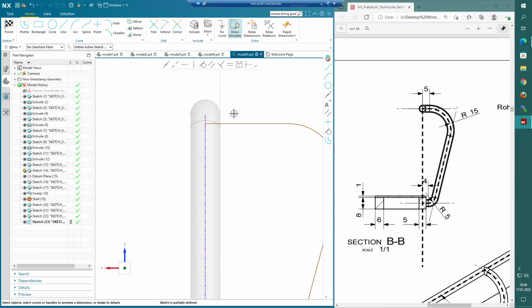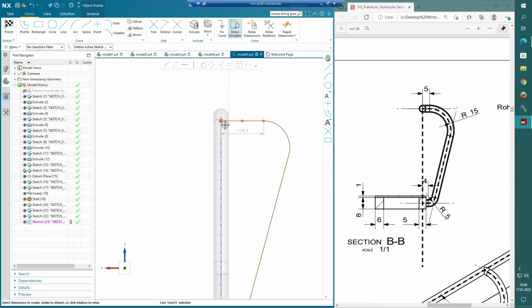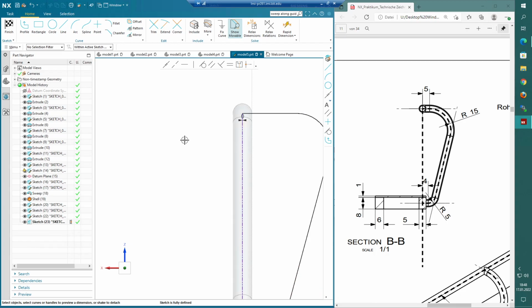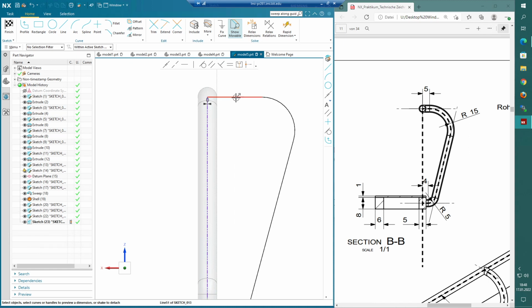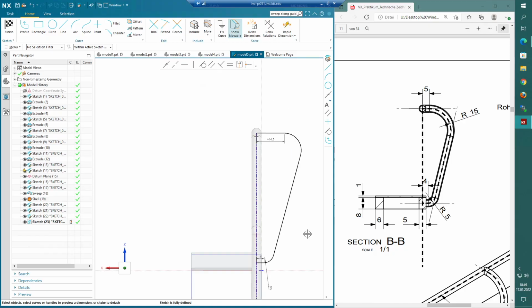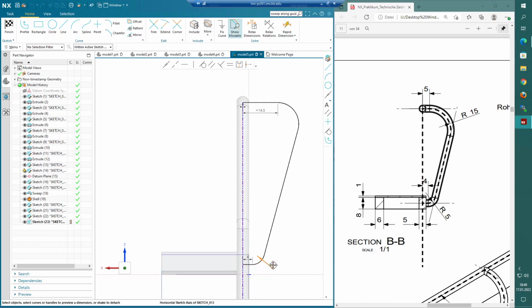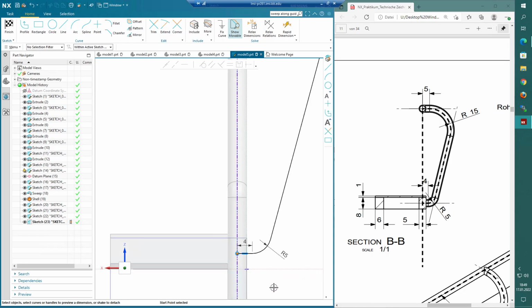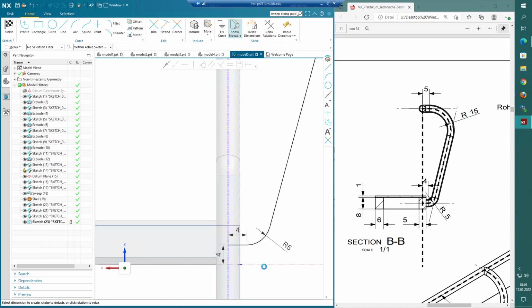And now we can take the endpoint and make the distance to endpoint right here a 0, because it has to end exactly at the middle of our other rail, that's for sure. Then this right here should be 5 only. Okay, doesn't let me right now because it probably has assumed some things that we don't want. We know that the start point should have a distance of 4. That's right, it should be exactly in the middle.